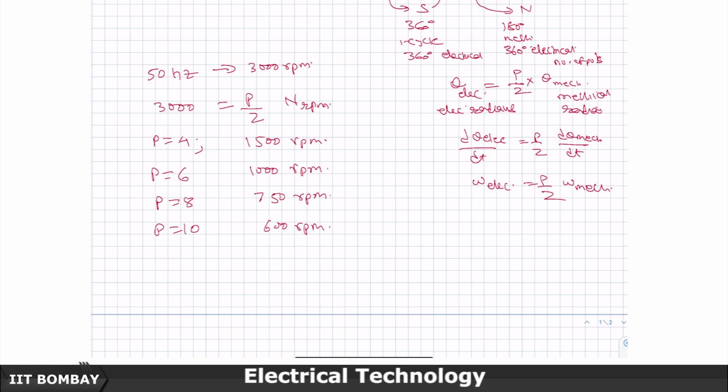Now, on the higher end here we have thermal generators. The steam turbine: the steam is produced in a boiler, where water is heated to steam, in fact it is superheated, it comes to the nozzle, it exits from the nozzle with a very high velocity, and it causes the turbine to run at a very high speed, which is 3000 RPM. We run that by the speed control mechanism at 3000 RPM, and that is really a high speed machine.